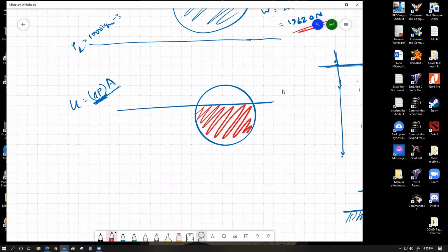So I'm going to write that equation over here. Upthrust equals weight. We know the exact weight. I calculated this to be 19620 Newton. How much would be the upthrust? Upthrust would be equal to the density of water, which is 1000, multiplied by the volume of the displaced liquid, which would be, by logic, the volume of the sphere that is under the water surface. This much volume.